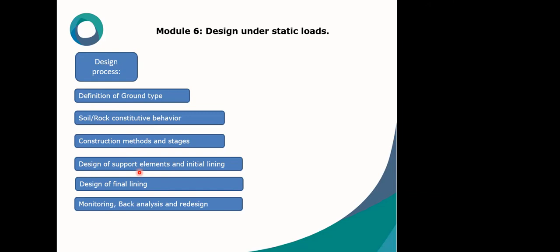In this part, we are going to talk about the design construction material properties in detail. For example, in the absence of the precise calculation, beam stiffness could be assumed 50% of the uncracked section of the mentioned beam in restrained frames due to the ACI.